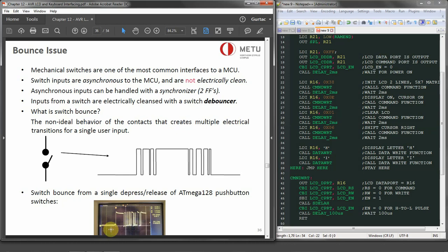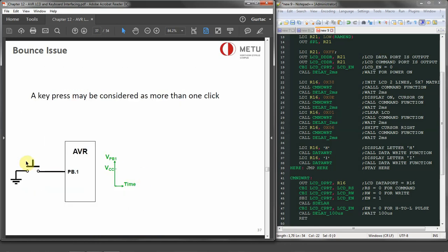We start to see, okay, 1, 0, and we start to see some fluctuations between ones and zeros on the electrical signal. This is actually a bouncing issue. That means we are not having valid values over there and it's just fluctuating. So we can say that when we have the button and we measure it over time, you will see that bouncing, the fluctuation on the button output.